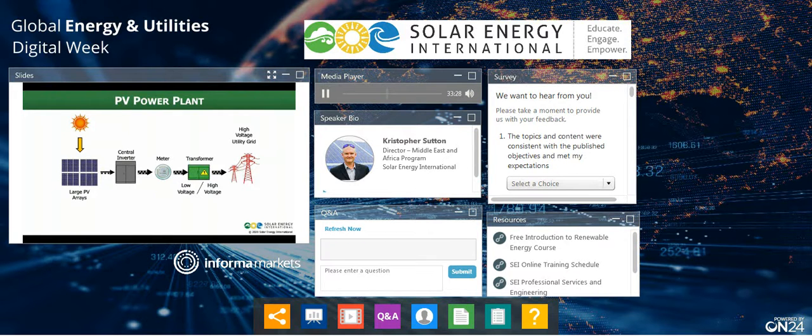Those big solar power plants, unless they have batteries with them, those inverters work exactly the same way. And the way we configure the solar arrays is also exactly the same way, just much larger. So we go to what we call a central inverter. Central inverters we use when we get into big, tens and hundreds of megawatt systems. Central inverters today are getting up to over 2, sometimes maybe getting close to 3 megawatts per unit. So maybe 500 kilowatts to 2.5 megawatts. That's kind of the normal central inverter range.